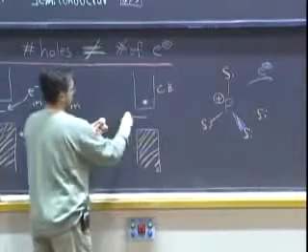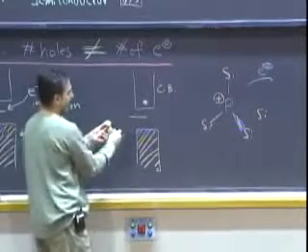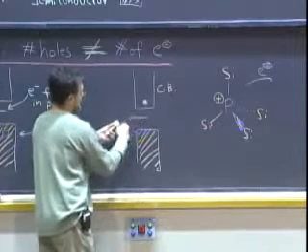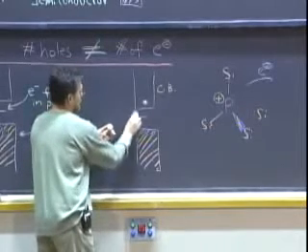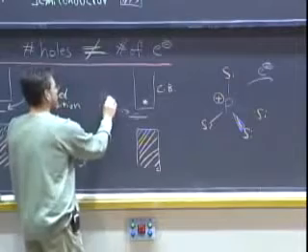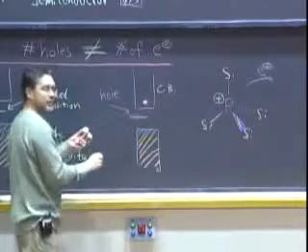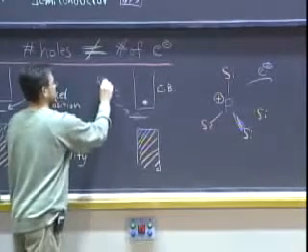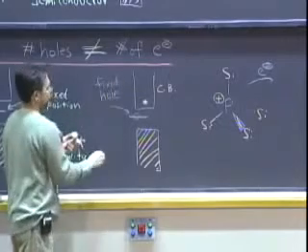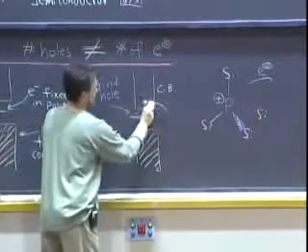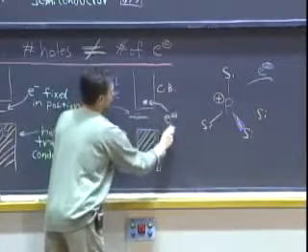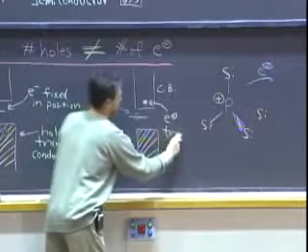So this electron jumps up off the phosphorus into the conduction band, and that leaves behind a hole. So you have a hole or a positive charge there fixed in position, and now you can have electron transport as your mechanism of conductivity up in the conduction band.